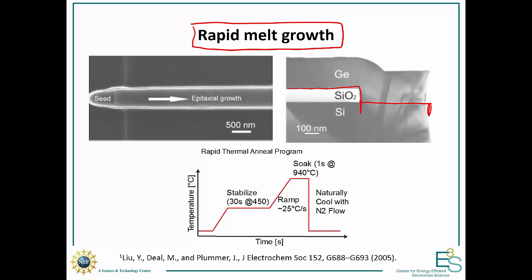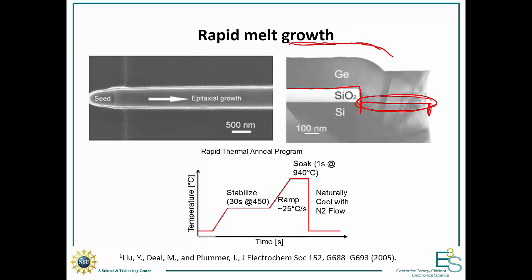So the germanium only sees the silicon crystal here in this area. So you deposit your germanium, you pattern it, and then you cover it entirely in oxide. So you're going to add oxide above here. You're going to have a layer of oxide that completely encapsulates your germanium.